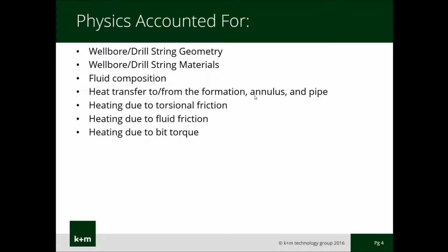The temperature in the well is computed based on the heat transfer to and from the formation, pipe, and annulus. Heat generated by the drill bit, torsional friction, and fluid friction are also taken into account.